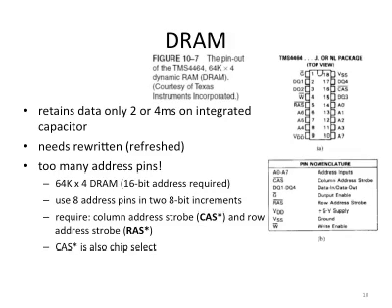So what you see here is 2 special control signals called column address strobe and row address strobe. And often the column address strobe is also the chip select. If you look at this DRAM chip, it has address inputs from A0 through A7.